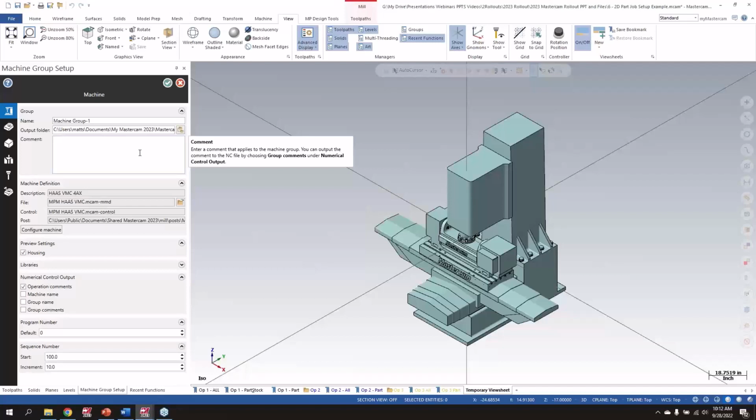And the interesting tidbit that he told me about this new interface is this is the first step to getting technology in the software that's basically going to keep making it smarter. So this is laying the groundwork, I'm trying to think of the best way to say this, laying the groundwork to make the mill files completely stock and collision avoidance aware. Like anyone now knows, say I'm doing a 2D dynamic toolpath, I still have to select my clamp or my fixture as like an avoidance.